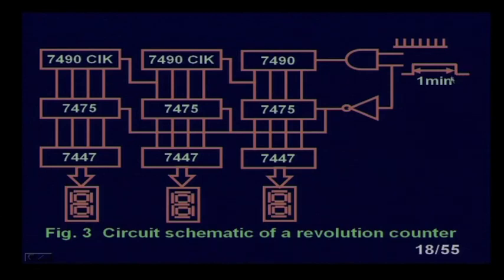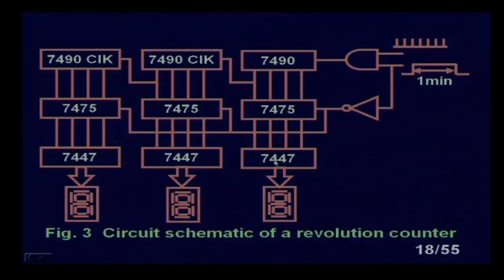Okay. So, when this falls, this will activate it because this will be 1. Whatever data we have at the output of the 7490 in the 4-bit will come to the 7475. Previously it will latch to the previous values. Then it will come to the display, do the BCD to 7 segment decoding, and appear in the 7 segment display, right. This way it will work.